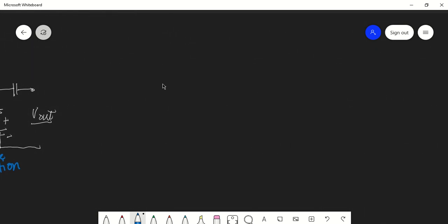Okay, so now before moving on, I must mention that you have to use the circuit that I will tell you here in this demonstration. Do not follow the circuit from your lab, because I think the DC biasing values of resistors are not correct in the lab. I tried to implement it, but I could not find the desired results. That configuration does not yield a proper amplification. So don't follow the circuit from your lab manual.